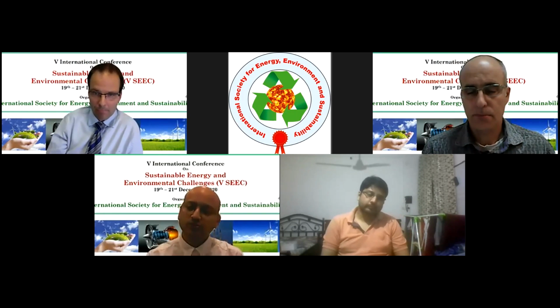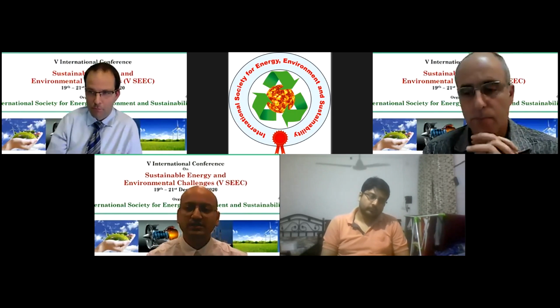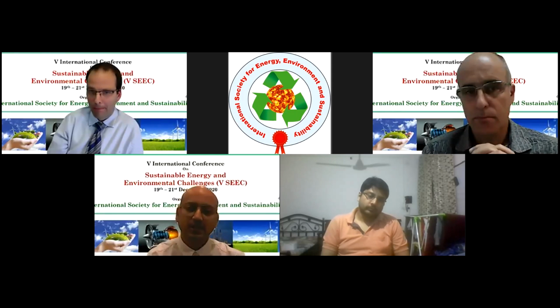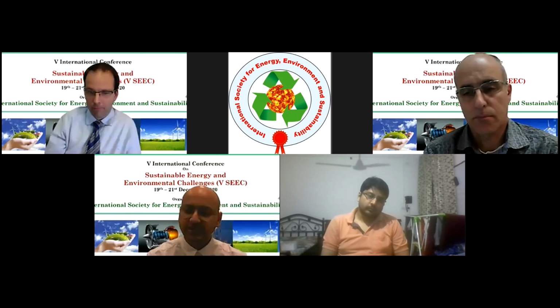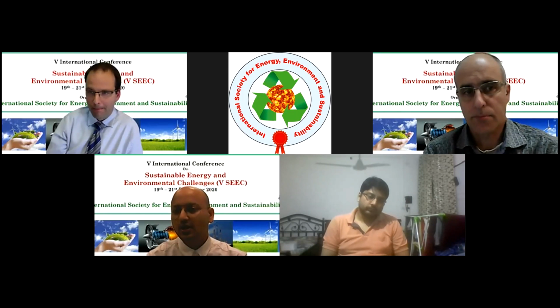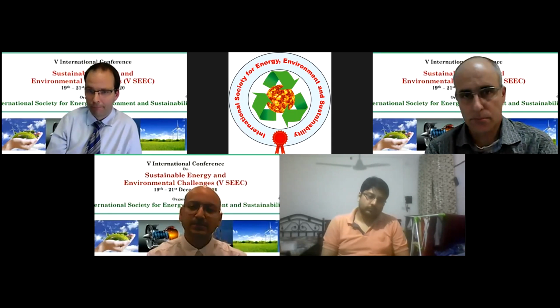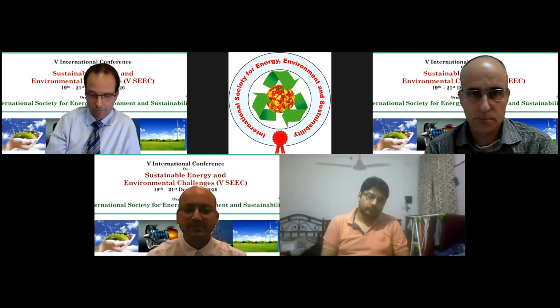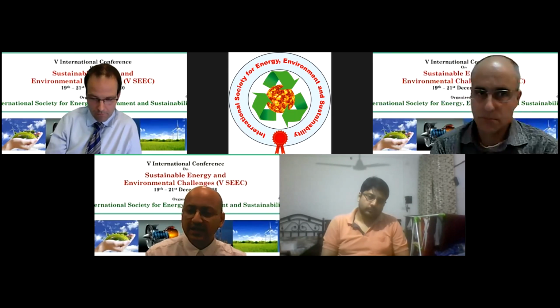I just want to add, on what Professor Arnush talked about, these electrically conductive membranes. There is a class of new membranes where at the same time as separation, we can do degradation. Possibly that can be a solution for these things, because for most of these emerging contaminants, given their smaller size and absorption properties, the rejection even through RO is not that great.